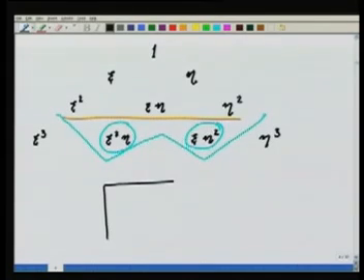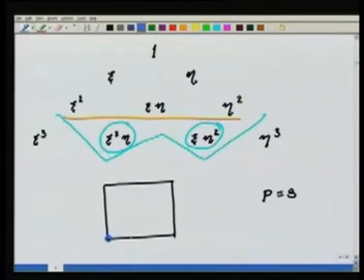Similarly, we can easily now continue this job and talk of the serendipity family of order 3. Again remember that the shape function should be such that on the edge they should represent the given order 1D shape function. So I will construct them using the 4 points on the edge, like this.